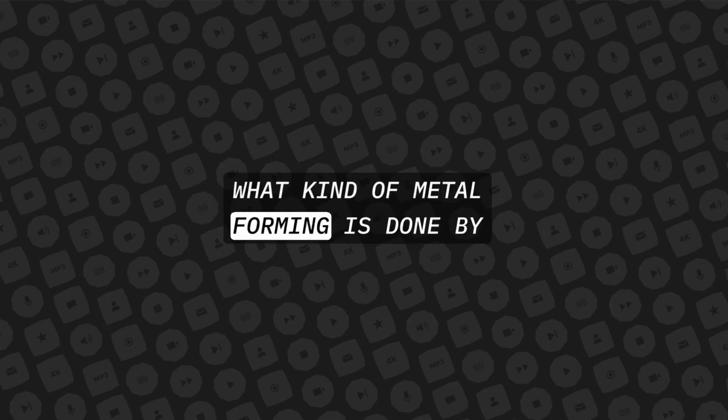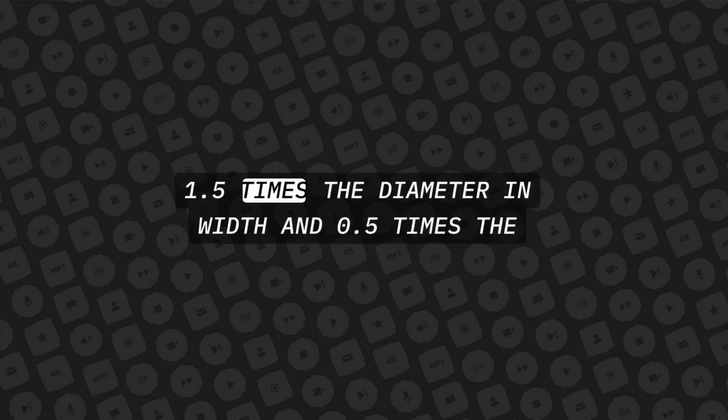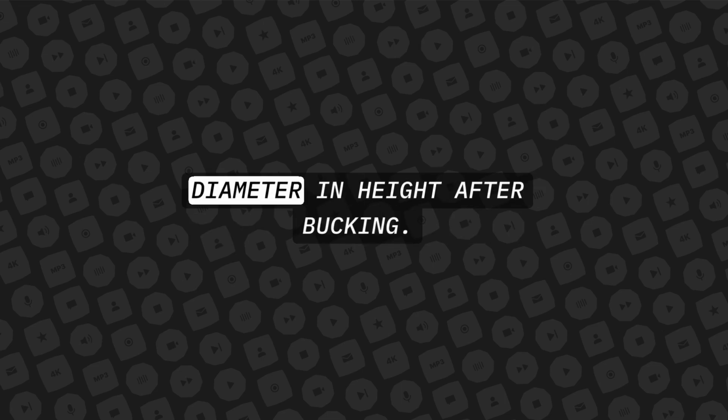What kind of metal forming is done by bumping? Compound curves. What are the proper dimensions for the shop head of a rivet? 1.5 times the diameter in width and 0.5 times the diameter in height after bucking.